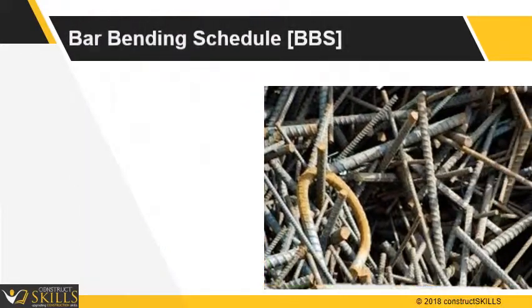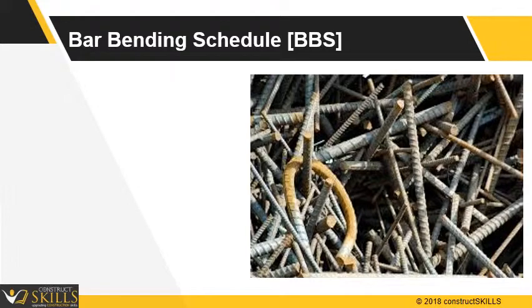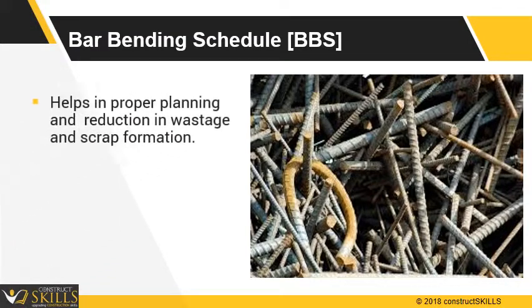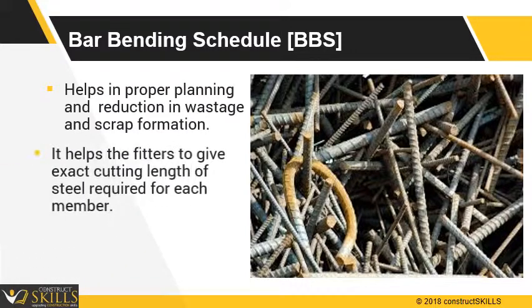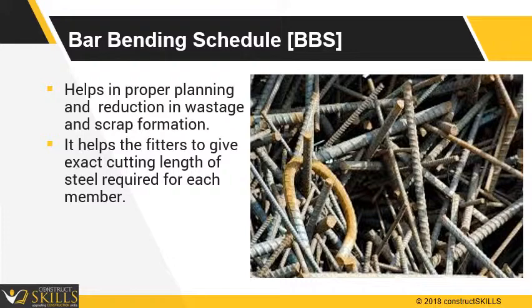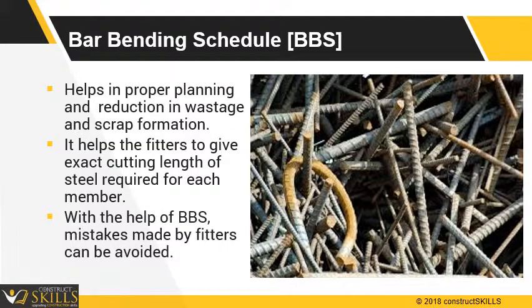Bar bending schedule is popularly known as BBS. It helps in proper planning and reduction in wastage and scrap formation. It also helps the fitters get the exact cutting length of steel required for each member, and mistakes made by fitters can be avoided.